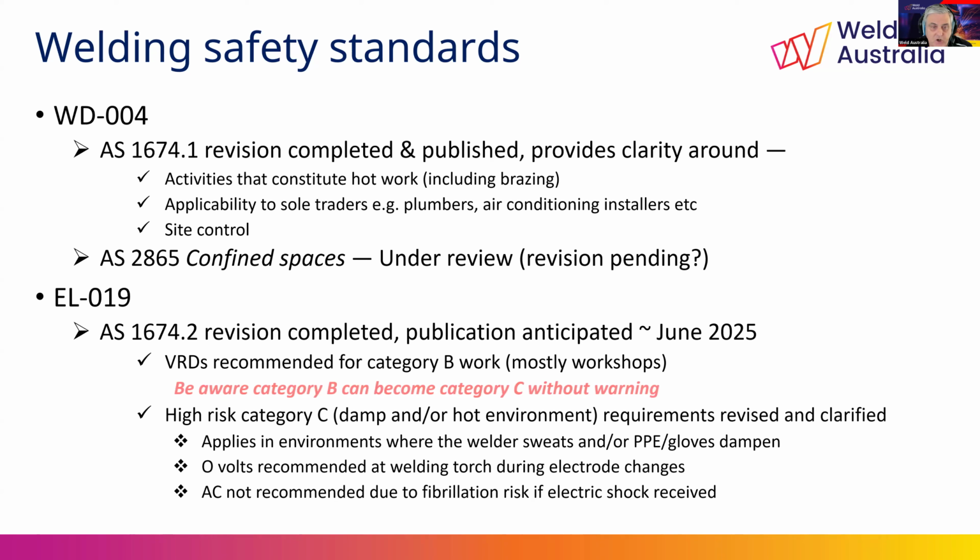The other significant change for people to be aware of is in Category B welding, at the recommendation of the Queensland coroner following an electrocution of a welder. We've recommended that voltage reduction devices be used, so as to limit the potential for severe electric shocks for welders in Category B environments.